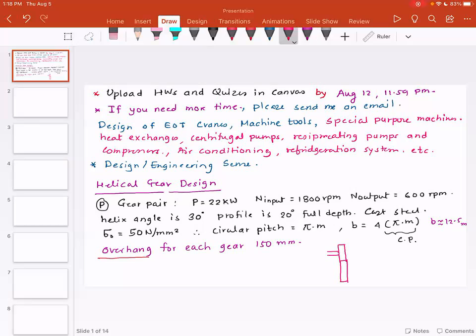They could be cantilevered on one side, they could be cantilevered on the other side. So this is how the gear configuration is, and this distance is 150 millimeter. And that could be some geometric consideration, for example, that the gears need to fit inside an automotive transmission, and that is the maximum space available to us.